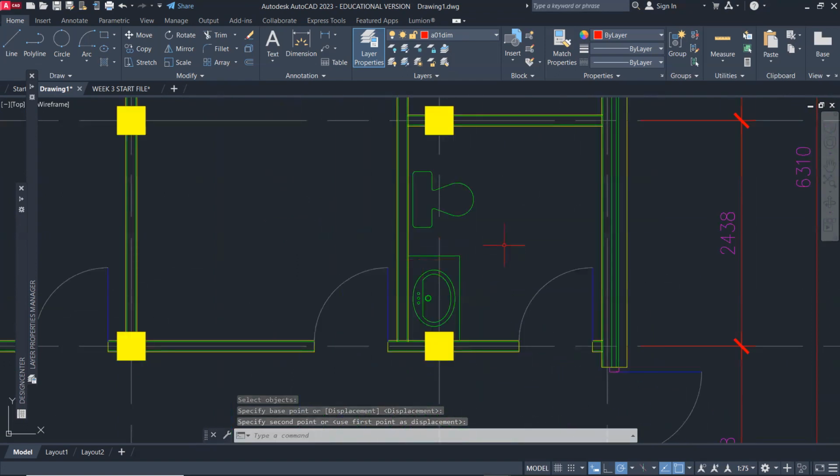Now notice I place the toilet and sink together rather than placing it here, so that when you do piping, you place the drainage and the water supply here on this wall instead of running it around. So drainage and water supply.